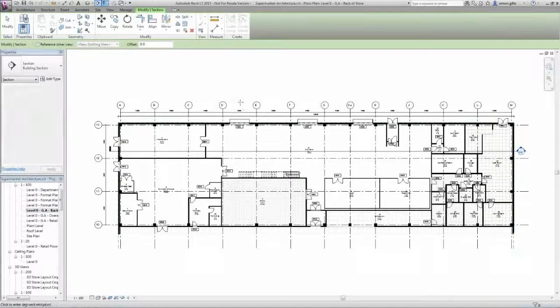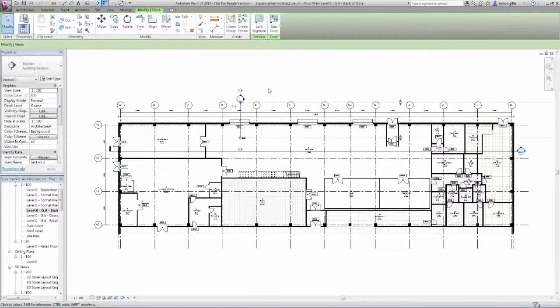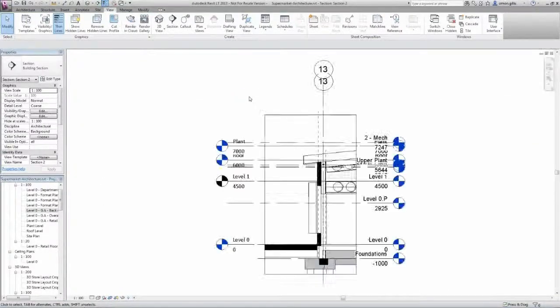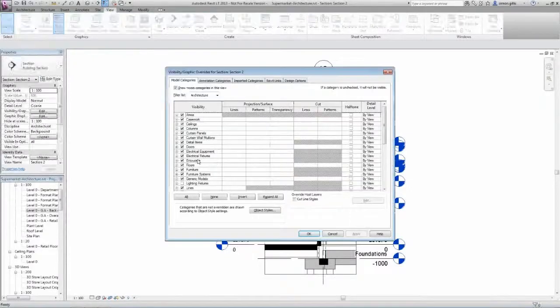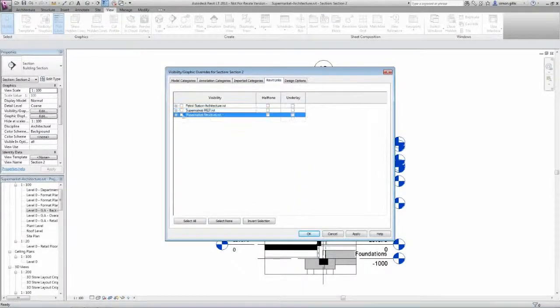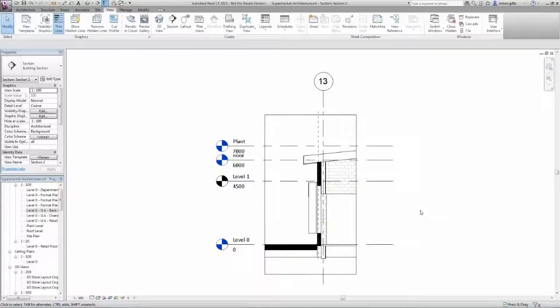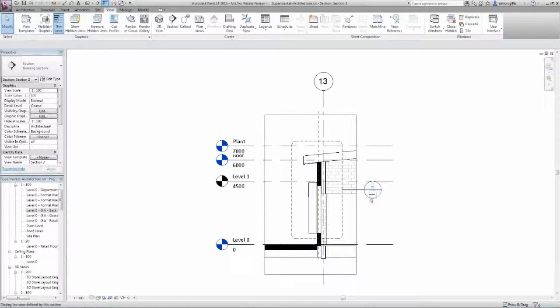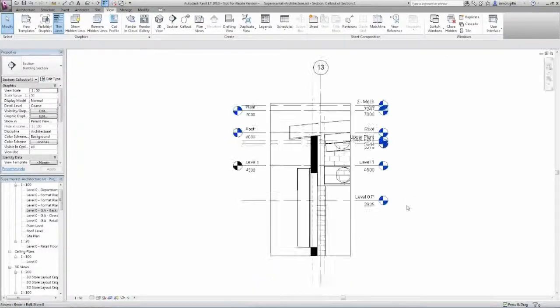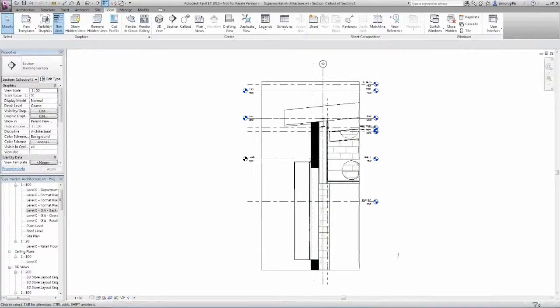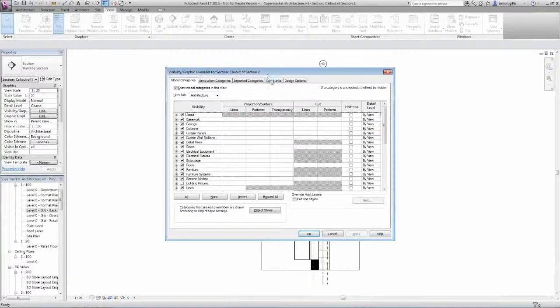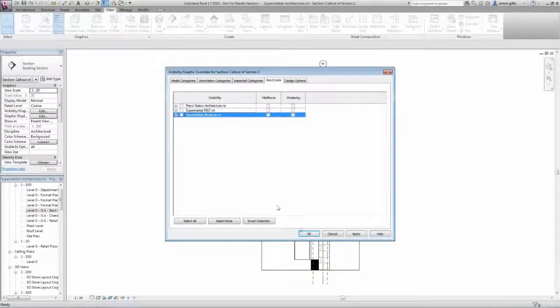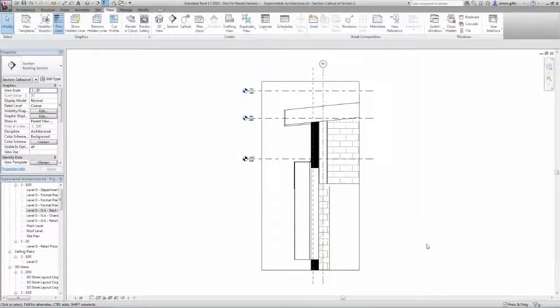Let's look at, whilst I'm on the theme of sections, I'm just going to draw a section through another part of the building here, through the dock shelter for the lorries to access. So I can go in and create sections. From those sections, I can also create call-outs. So I can go in and zoom into areas of those sections. I can open that automatically. I can change the scale. Notice if I change the scale, it automatically updates aspects such as the notation. So I only have to specify, for example, 2.5 high text. It will always be 2.5 high text.